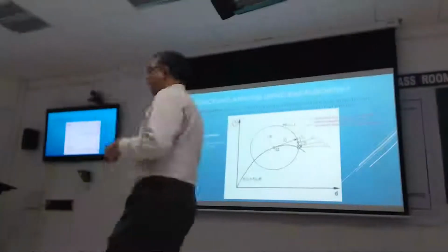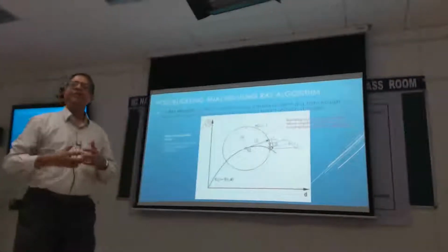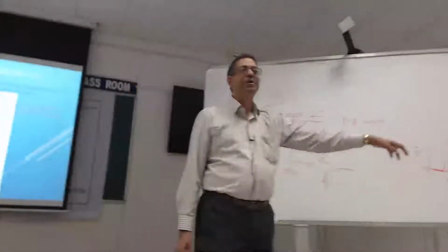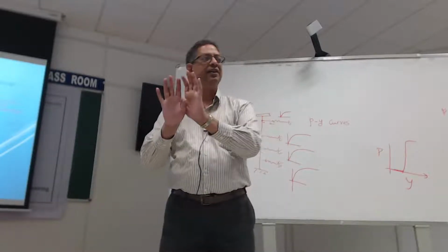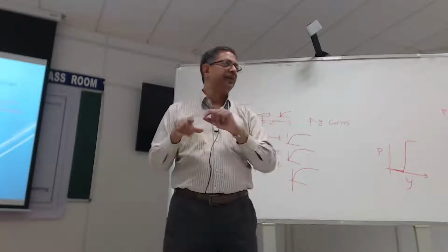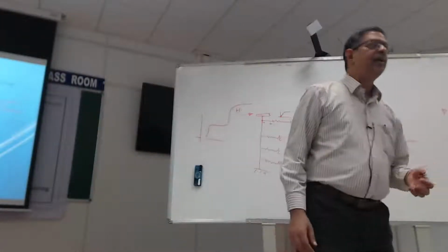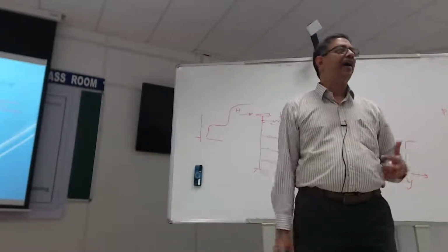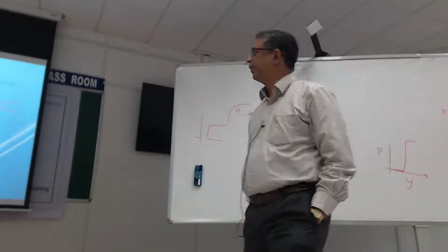The problem is not that we can't do those p-y curves. The problem is finding the solution. If you write a code like this and give that shape, it will never converge because it's always trying to hunt for the displacement it needs to apply to find a pressure, and it finds either the pressure is too much or too little, and it goes in circles. So convergence becomes a problem. That's true even if you run a numerical analysis. For example, we had a go with Abaqus, and for ages Jonathan Knappett could never find the answer because it just crashes after trying and trying and gives up because convergence can't be found.